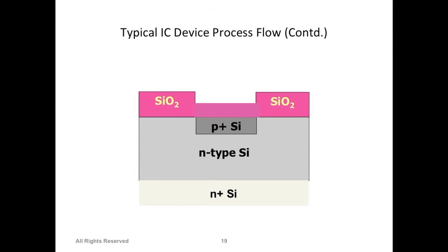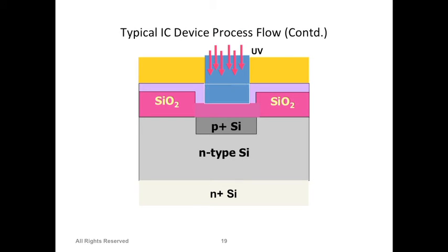Then let's say after that I do lithography, the photoresist. After the photoresist deposition, I put a mask on the surface, and then I expose it, so the pattern will be transferred after development inside the photoresist. Now I want to transfer that pattern, this opening, into the silicon dioxide. What chemical can I use for that? I want to etch silicon dioxide from this area, right? So what acid is used for silicon dioxide etching?